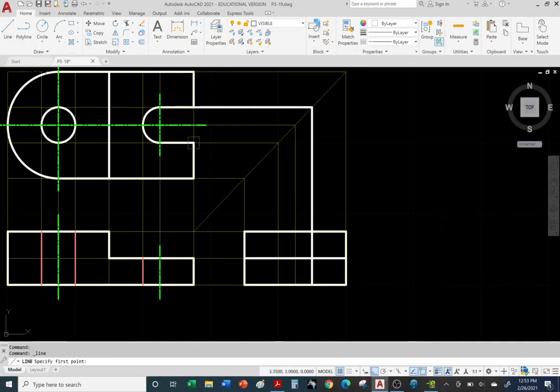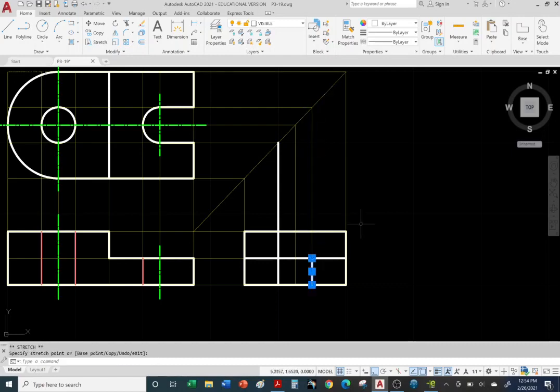And repeat the same thing on the opposite side. There it is, and straight down. You don't have to do all this geometry. I'm just showing you how everything lines up. So we can go ahead and delete the portions we don't want. Delete with the pencil, number two pencil eraser. And let's correct the height of these object lines using the grips. There they are. I'm going to hit escape. We're almost there.